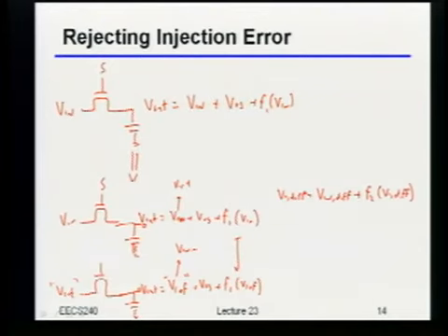So now the only thing that I have left that I still need to probably fix, or potentially fix, is this darn thing. Right? Because I still have this distortion that actually depends on the input voltage. Okay, and by the way, if I'm shooting for like 10, 12, 13 bits, particularly at high speed, this could actually be a big impact on things.